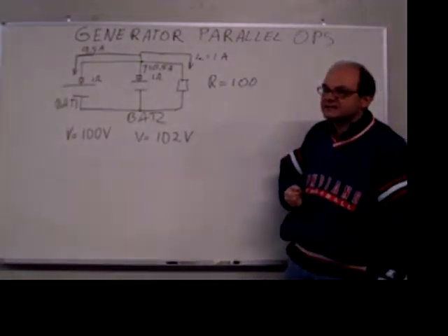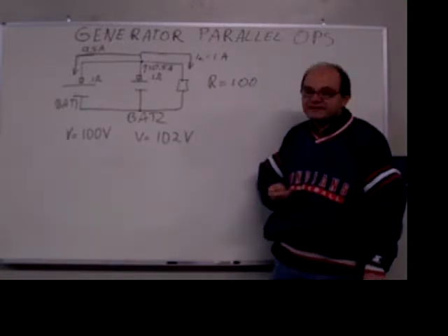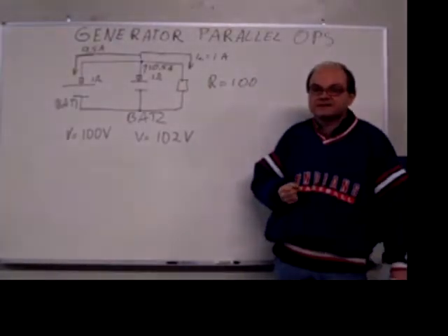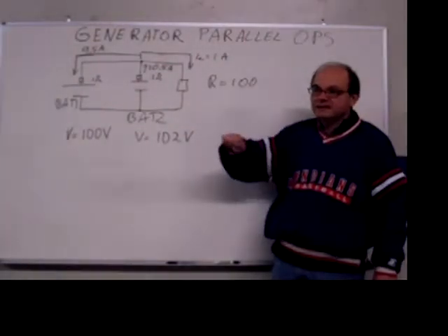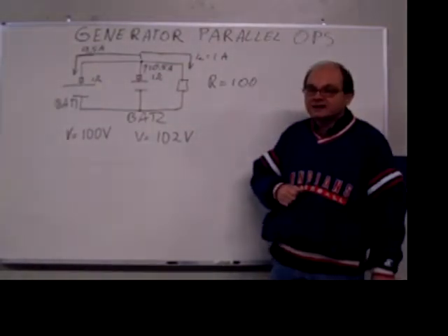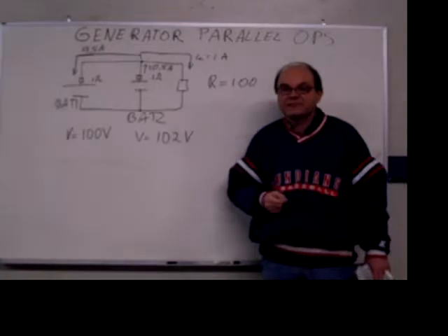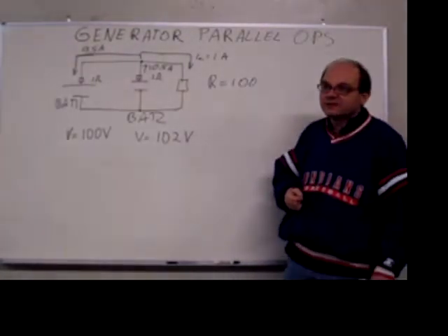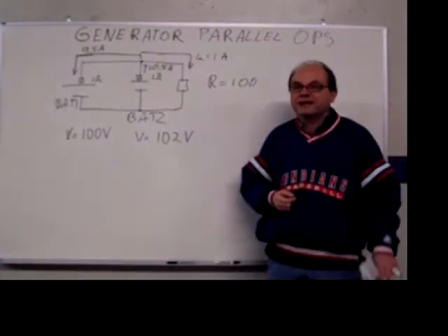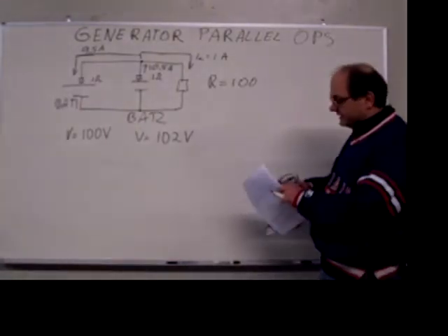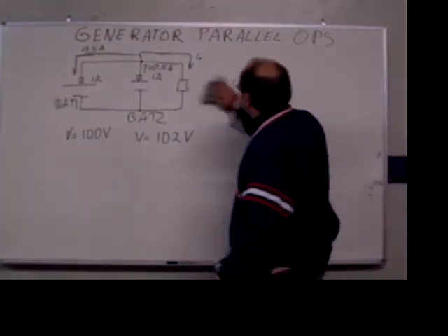That is definitely possible. It requires some major rewiring of this entire set, and you would lose basically the rheostats which you have on there. So that means once this thing is basically wired for parallel operation, you will not be able to really run this on a single generator by itself. That's kind of where that is. Now let's talk about the other issue in this.